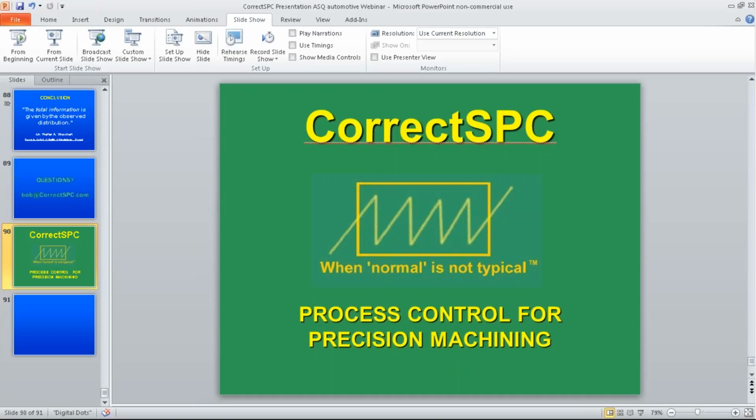Okay, here's another one. Loss function seeks least variation about nominal based on cost of deviation from nominal. In that respect, automated tool wear adjustment could be desired. It seems tracking the compensation over time against the theoretical compensation could be useful. Comments? Well, in order for it to be of any value, it's really doing the same thing as a person constantly running to the mean. They're going to totally lose track of what's going on with the tool wear rate because they have become the process rather than the process, which is tool wear. Whenever a person becomes a process, that's not really good.